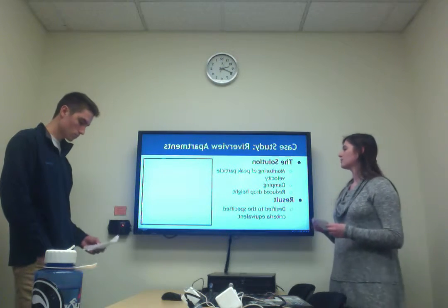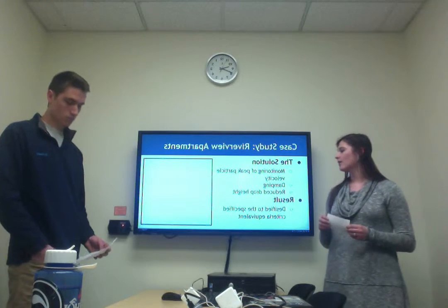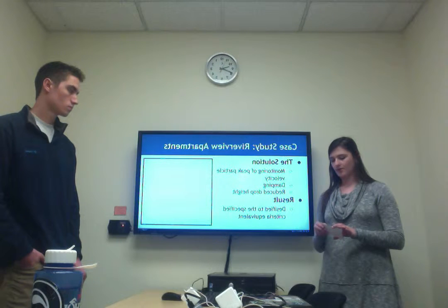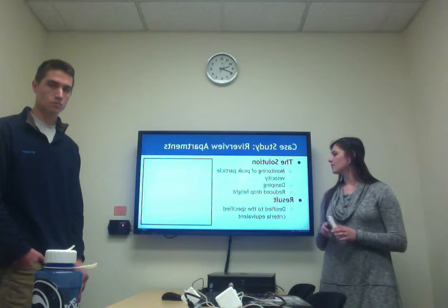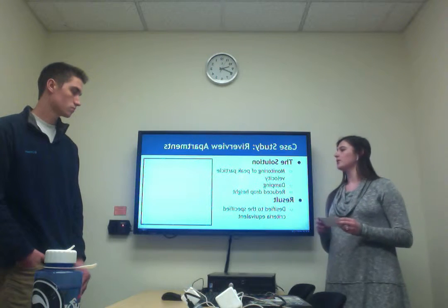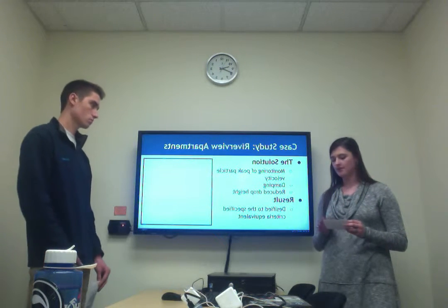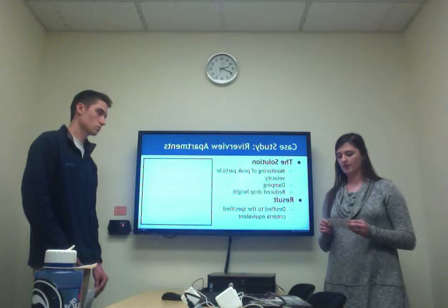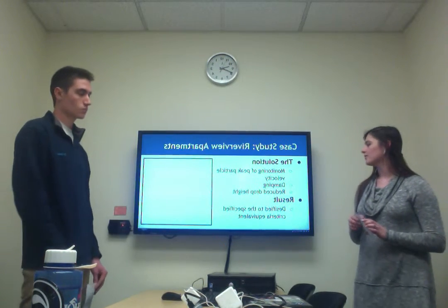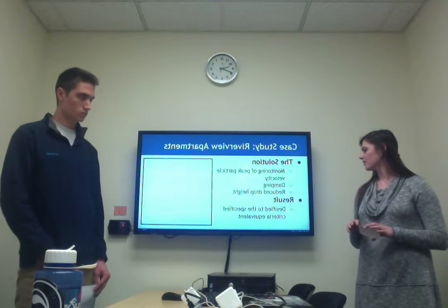So in order to continue the compaction, all they had to do was lower the dropping height of the compaction, and then the other structures were in acceptable tolerance of 0.5 inches per second, so they could go ahead and keep doing regular compaction for the rest of the site.